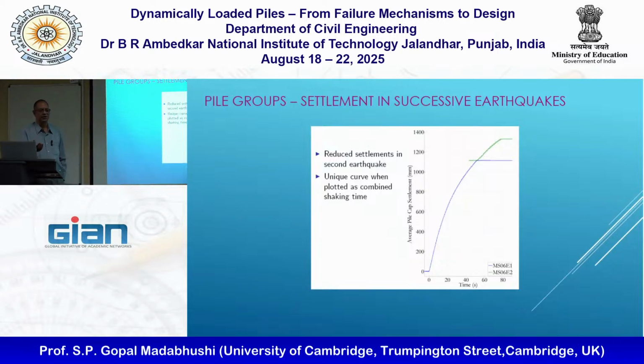If you ask the structures guys what they'll say, settlement is settlement. By the time you got 1.5 meters of settlement, the pile is dead, the structure is dead. This is not interesting for us. But for geotech people, this is interesting because that tells you something very fundamental about the soil. So in successive earthquakes, it remembers.